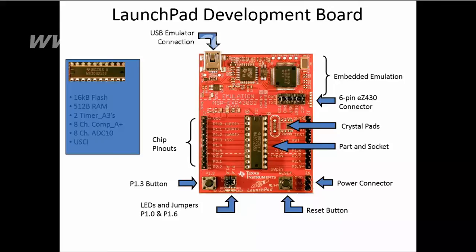The pinout shows basically which interior functions are connected to each pin of the package. Perhaps the most obvious feature is that almost all pins have several functions. This is typical of a modern small microcontroller. Silicon is cheap, but pins are expensive. The aim is therefore, as you all know, to integrate as many functions into as small a package as possible. Most applications do not use all the peripherals, so with good luck there is no conflict where a design needs more than one function on a pin simultaneously, to avoid ambiguity.